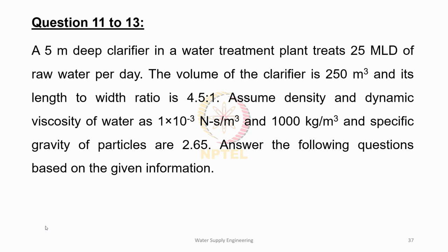So we are given a 5-meter deep clarifier, and per day it treats 25 MLD. The total volume of the clarifier is 250 meter cube. Length to breadth ratio is 4.5 to 1. Dynamic viscosity, density of water, and specific gravity of particles are given.